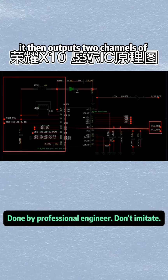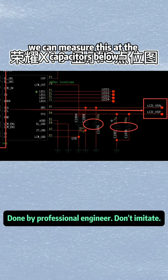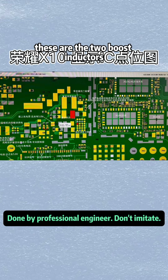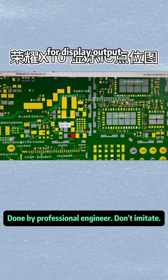It then outputs two channels of 5.5V each for display power. With the screen connected, we can measure this at the capacitors below. Switching to the point map, let's check it out. These are the two boost inductors. We need to measure the main supply voltage here. These two capacitors should be plus or minus 5.5V for display output.